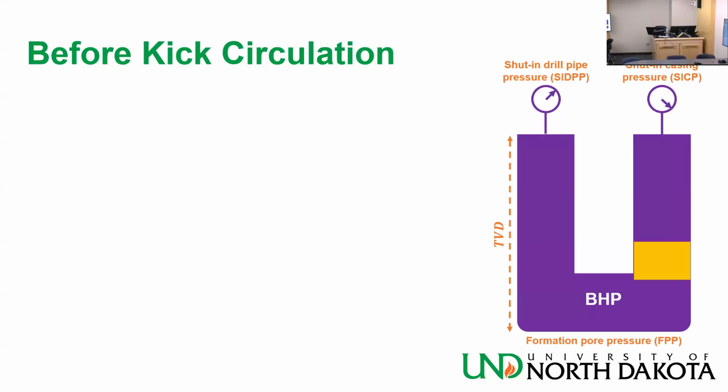If the volume is increased, it could be taller. And how far it goes depends on the annulus there. You are expecting it to become taller as it goes up. If it becomes taller, it takes more space. It has a lower density than the mud. Remember, in the U-tube model, it only cares about the height. It doesn't matter about the hardness or anything. Everything depends on the height, hydrostatic.